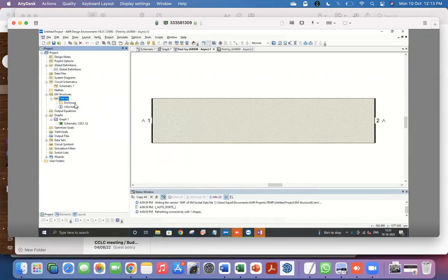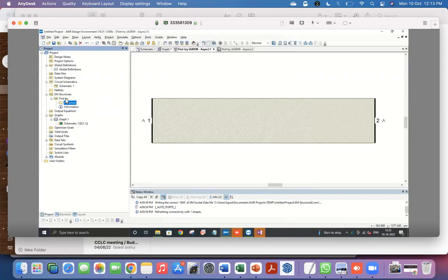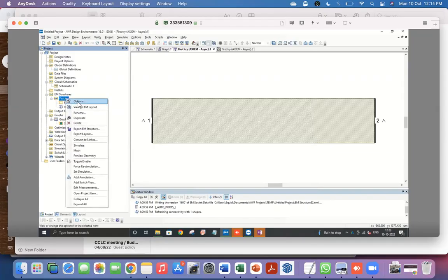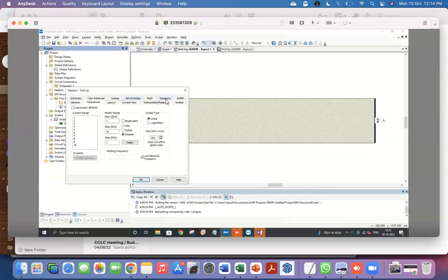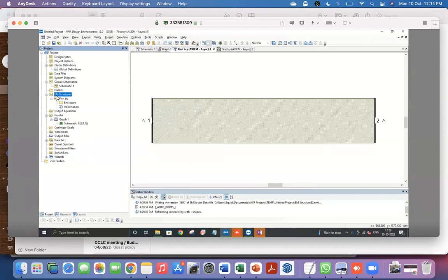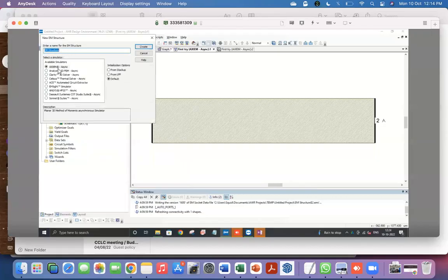There is another catch here, and this is something you have to be careful about. Because I didn't create the EM structure again today from the beginning. We had looked at it last time at the end. Let me just go back. It's got to do with this solver. Remember when I created the EM structure? In fact, let me just do one to show you. When I say new EM structure, it pops up this window with a list of simulators. And then we chose this first one, XEM.